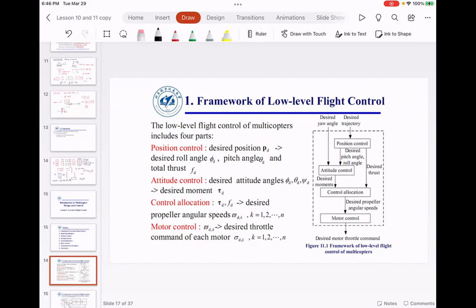It's going to do something called digital image correlation, which is called DIC, and it will tell you how far the Mambo has moved forward, left, or left positive, left negative. Now, what happens when the Mambo is going to go up and down? Again, you have an accelerometer in the z direction. You can doubly integrate the acceleration in the z direction. That will give you its height, so its altitude. And in addition to that, there is this ultrasonic sensor that will give you distance from the ground.